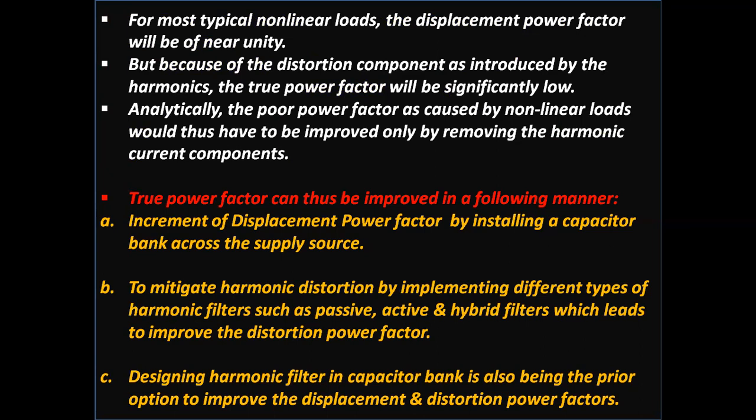B, to mitigate harmonic distortion by implementing different types of harmonic filters such as passive, active, hybrid filters, etc., which leads to improving the distortion power factor. Designing a harmonic filter in a capacitor bank is also a prior option to improve the displacement and distortion power factors.